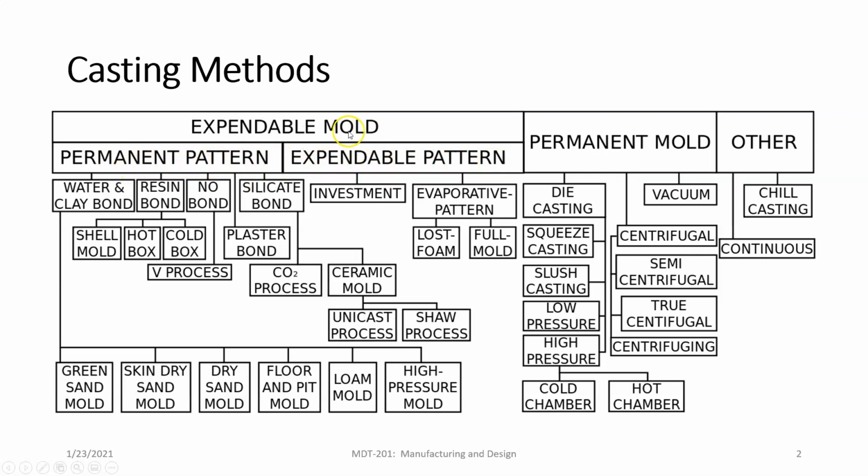Patterns are different than molds. Patterns are what we create the mold around. We can have a permanent pattern, which is kind of the more common method here, or an expendable pattern. That is, the pattern is also destroyed when we're making the casting itself.